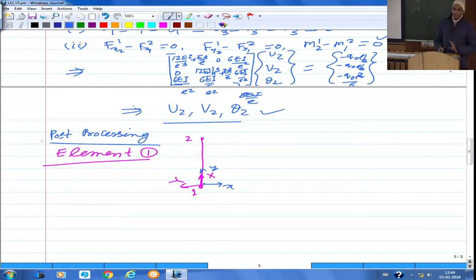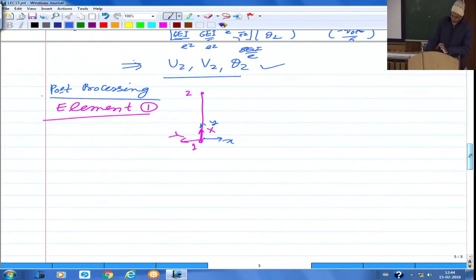Now what we want is, see, because when you want to get these stresses, in terms of the cross sectional properties, we will have to calculate the stresses and strains with respect to the local coordinate system of the element. So what I would need is epsilon xx, with respect to local coordinate x.